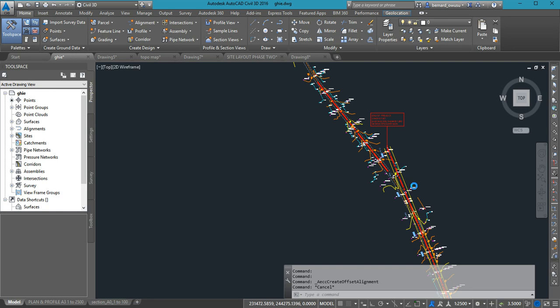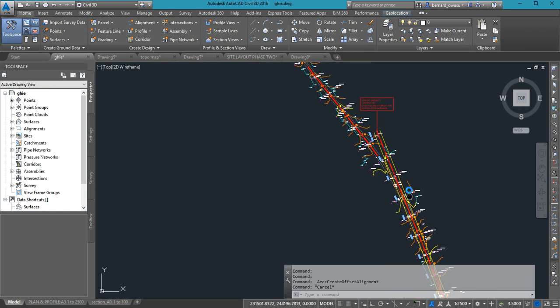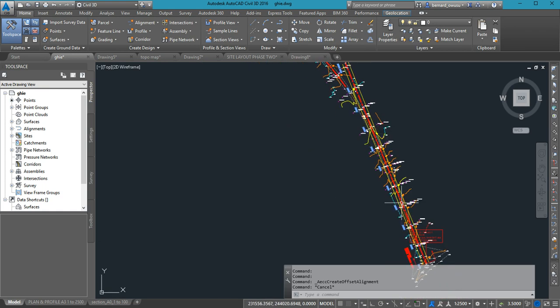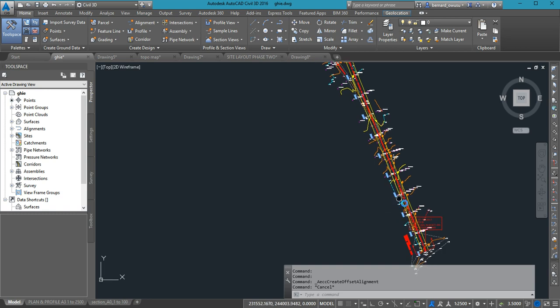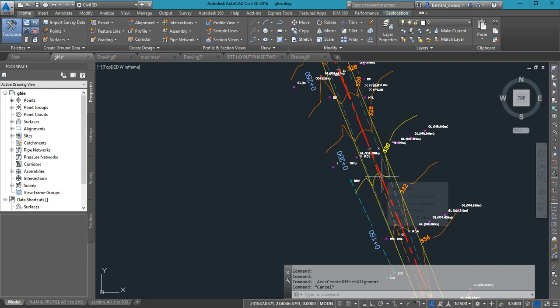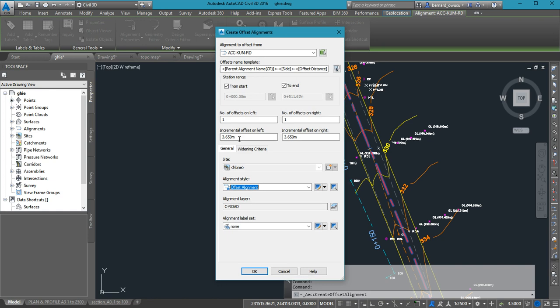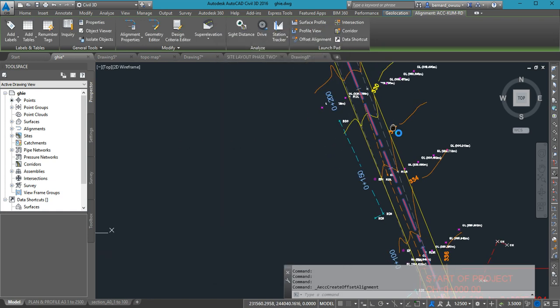So we have our center line. Now the next thing we want to do, we have our tangent. You don't have the offset. The line is not showing. Is it showing for the first alignment? I said select the alignment, and you see offset. Always look up, see offset alignment, select. Then you specify the left and the right, 7.15, 7.15. Click on OK, and you should see it.